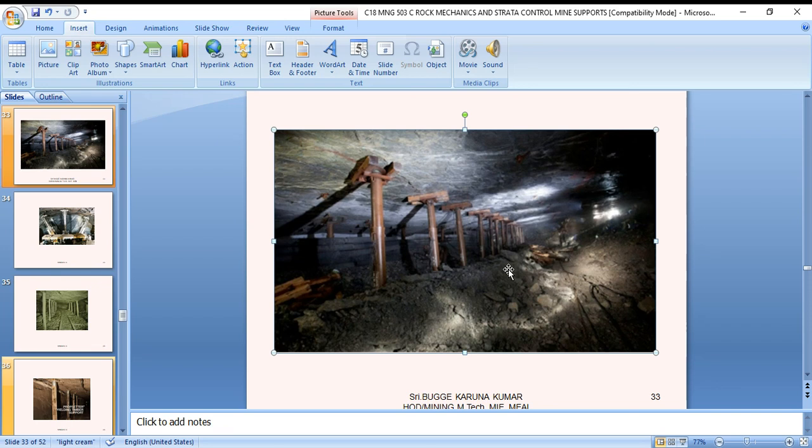In flat seams, the prop is erected vertically, and in inclined seams, the axis of the prop should be normal to the dip of the seam. The prop then offers the maximum resistance to the roof. A prop which is so set that it exacts between the vertical and normal to the seam is known as an underset prop. Erection of an underset prop is not common. It is possible for the timberman to judge whether it is underset or not.